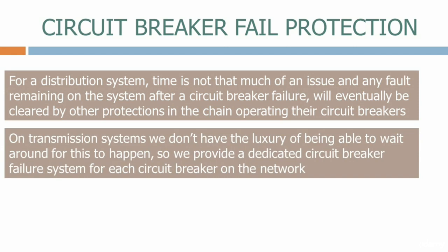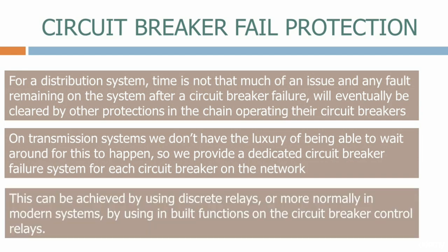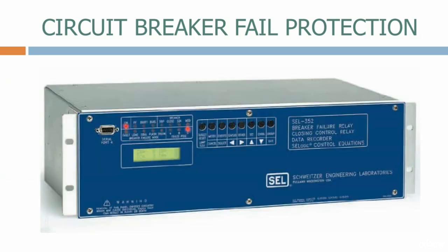On transmission systems, we don't have the luxury of being able to wait around for this to happen, so we provide a dedicated circuit breaker failure system for each circuit breaker on the network. This can be achieved by using discrete relays, or more normally in modern systems, by using inbuilt functions on the circuit breaker control relays. Here's a typical multifunction circuit breaker control relay.